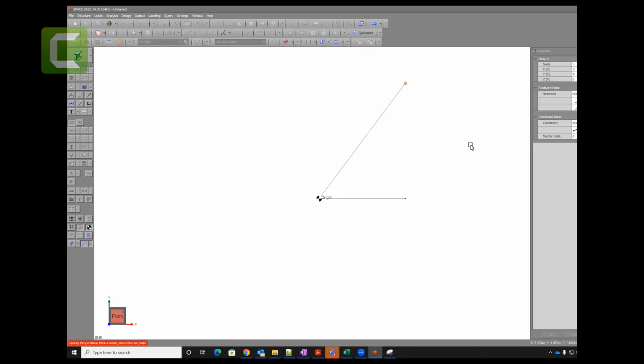When you go close to this point, it will just come back to the green round. Click on here, single click or just escape, just double click. When you have highlighted green, double click. You have different restraints. Restraint means boundary conditions. It has no restraint at the moment. It is fixed. Let me explain those letters. There are 6 letters you can see. Sorry, you can see F, F, F, F, F, F.